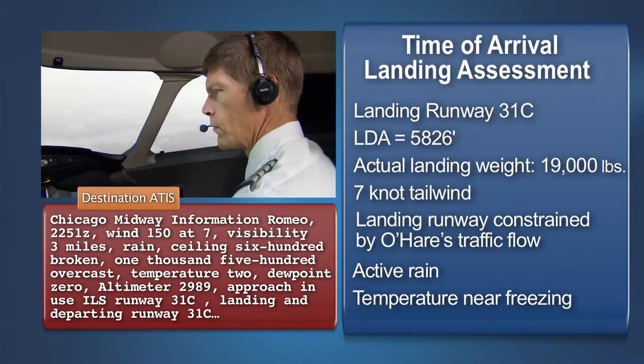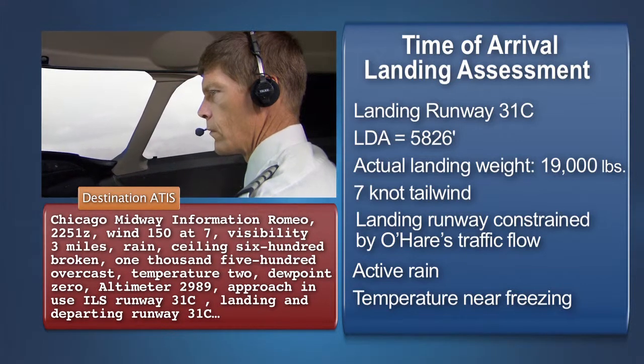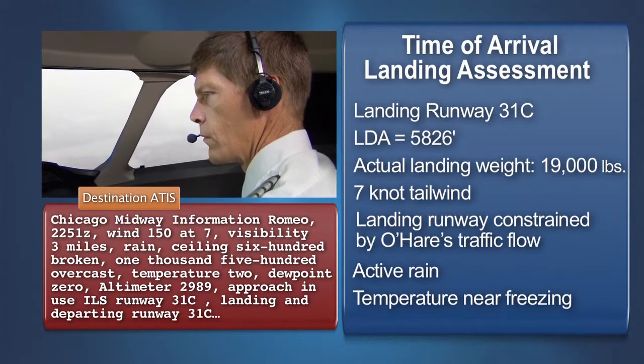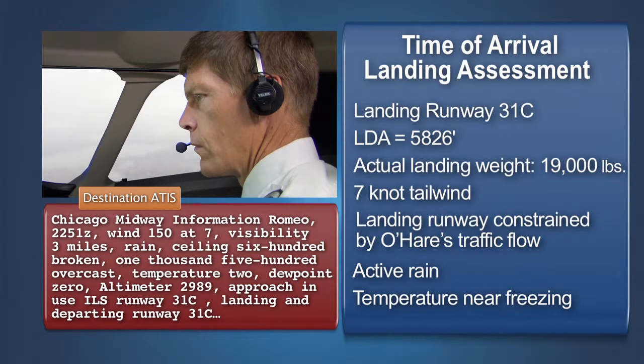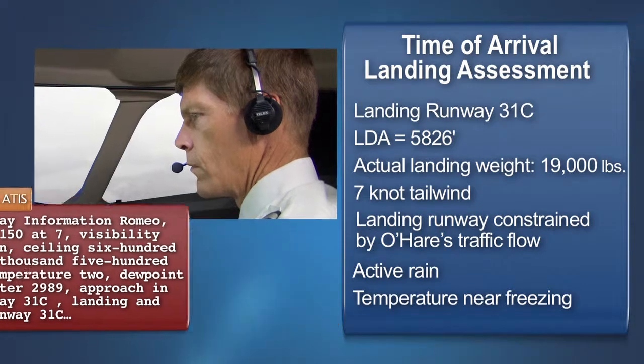When conditions are such that the runway surface conditions vary along the runway, such as braking action fair first 2/3 but poor the last 1/3, then the most conservative or worst condition for the portion of runway to be used should be used for the landing distance assessment.